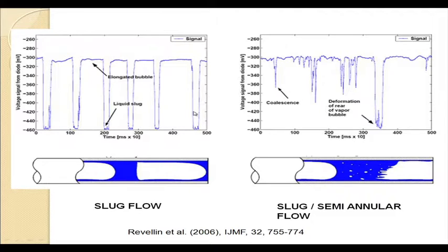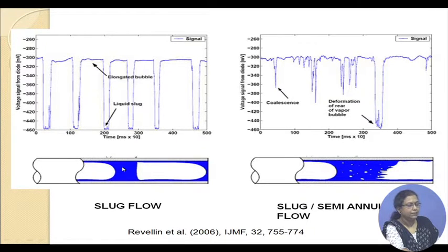very clear. And more importantly, since the liquid slugs are almost unaerated, as a result we find that it is almost a square wave type of signal. If the noise can be eliminated, it becomes almost a square wave type of signal, where we can very well see large peaks and small tapered valleys, which naturally shows that now large Taylor bubbles and short liquid slugs are traversing the path of the laser ray or the laser narrow beam.